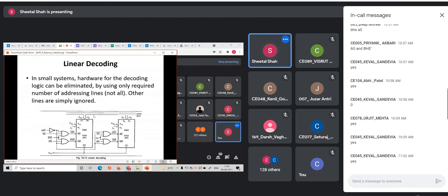So that means for a particular memory location in any of these RAM ICs, it may have multiple addresses, because A18 to A14 are different. Is this clear? They can vary. Suppose I take the example of A18, which is 0 or 1.